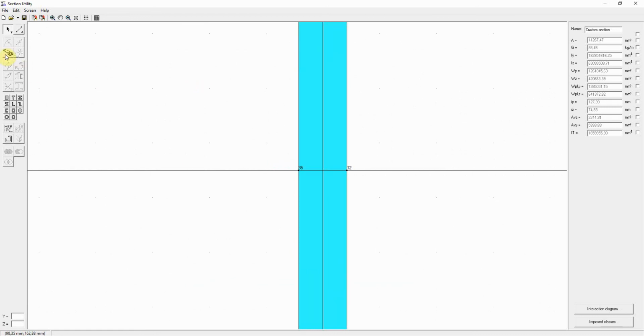and I'm going to use the saw function, the cutting tool. Activating the cutting tool is very important now that you start on point number 35 and you keep the mouse button, the left mouse button down until you reach point number 12, and there you can release the mouse. And by doing this, you see that there is an additional node added.